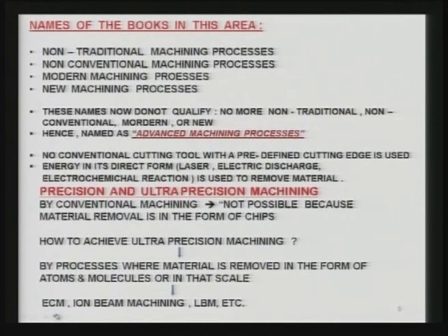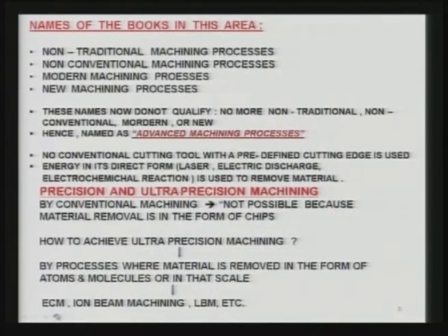In these processes, no conventional cutting tool with a predefined cutting edge is used, just like we all know the single point turning tool or milling cutter, etc. In these processes, energy in its direct form is used, just like laser energy, electric discharge energy, electrochemical reaction, etc. are used for the removal of the material.